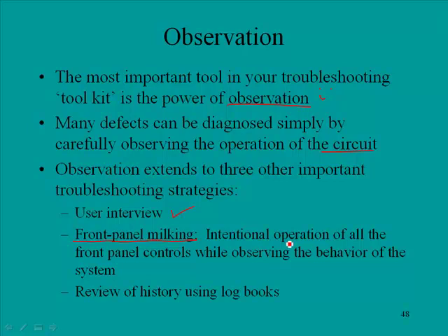It is the intentional operation of all of the front panel controls while observing the behavior of the system. This simply means that you're putting a given system through all of its paces, adjusting it and doing all the things that this system should be able to do, and observing its operation. Again, this is only going to be helpful if you know how that system is supposed to operate. If you know how it's supposed to operate and then you notice something that's not quite right, as a technician you'll be able to pick that up. But if you do not know the correct operation of a given system, this may or may not help.